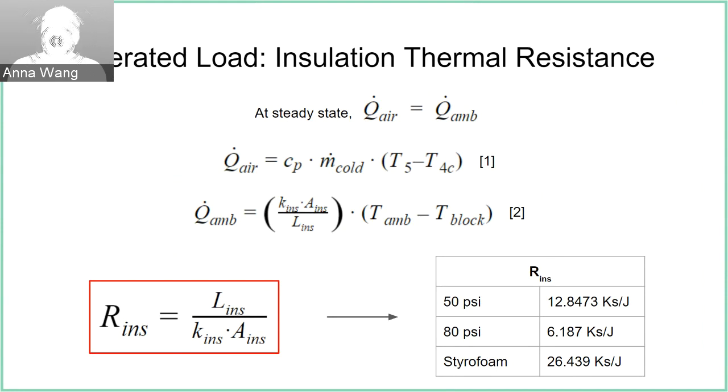We found that thermal resistance was higher at 50 psi than 80 psi, and that both of them were lower than the thermal resistance of styrofoam. This may be because the insulation in our cooling system doesn't cover the top of the block.